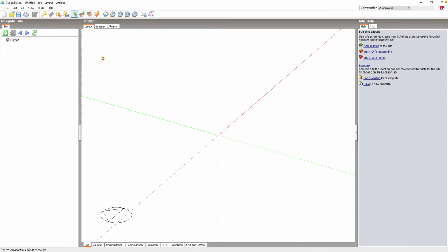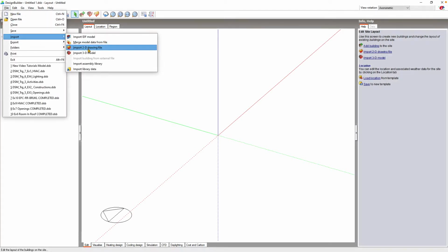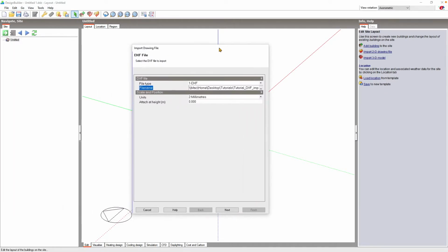DesignBuilder enables you to import DXF files plus a number of bitmap file types. These can be seen by navigating to the Import menu. You can import DXF, PDF, BMP, JPEG, GIF and TIFF files. Note that bitmap drawings contain no attributes, so they often need to be scaled and also do not have the data to use endpoint snaps. However, they can still be an effective option for rapid geometry entry in DesignBuilder.